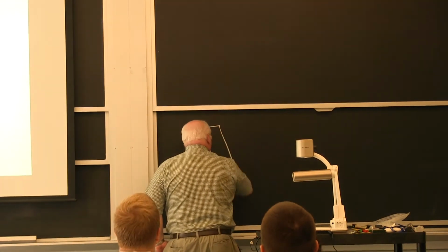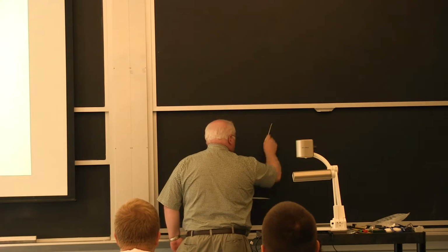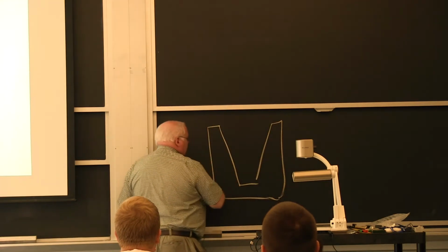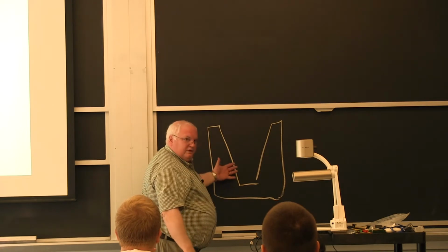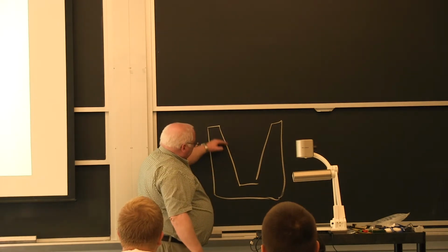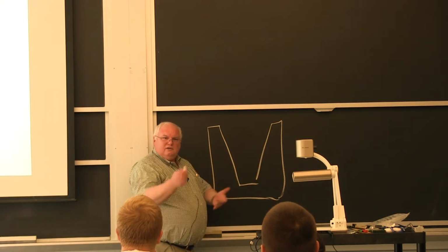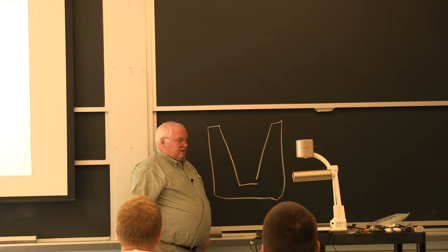So if I've got an ingot mold to make steel, I'm going to pour it into this mold. It's a piece of cast iron, a great big piece, maybe weighs 30 tons, and it's got sloping walls, so when it cools and contracts I can turn it over or pull it out without sticking to the walls.